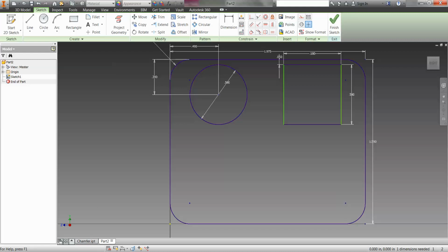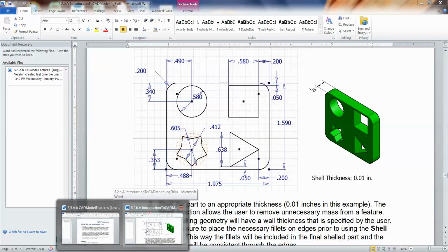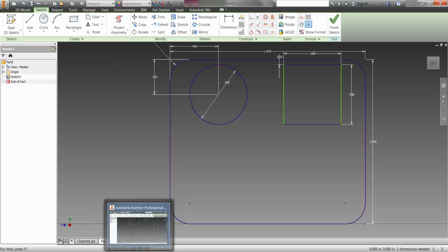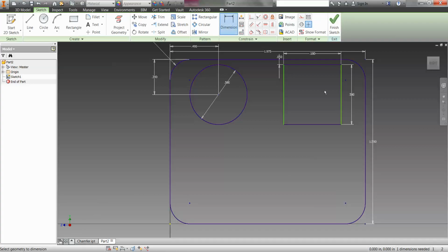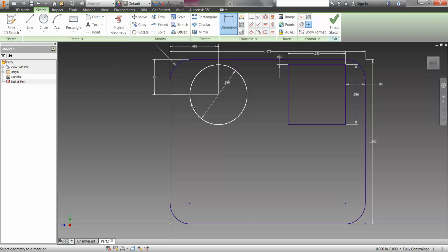It's better now. So let's check the dimension to the side, and it is 0.200 inches from the side. So that's what we're going to move next, is dimension that in at 0.200. Now, often as we put dimensions in, where we place the actual dimension just simply needs to be away from the shape. Be careful now, all these white lines are dimension lines. We don't want to work off of them for creating other shapes or figures or distances. So make sure you're paying attention to what's an actual object line and what's a dimension and extension line. Those are different things. We've discussed that before.